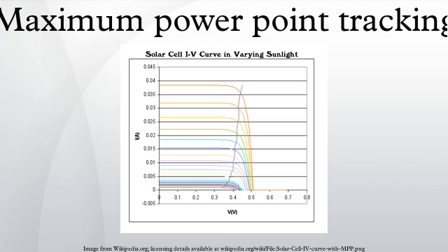One of the inherent approximations to the constant voltage ratio method is that the ratio of the MPP voltage to VOC is only approximately constant, so it leaves room for further possible optimization. Comparison of methods. Both perturb and observe, and incremental conductance, are examples of hill climbing methods that can find the local maximum of the power curve for the operating condition of the array, and so provide a true maximum power point.